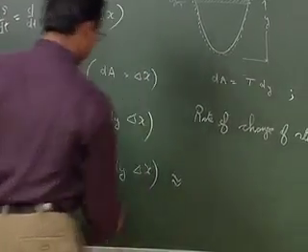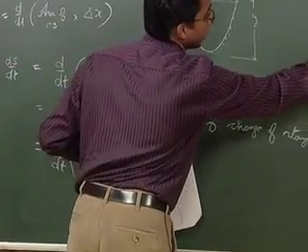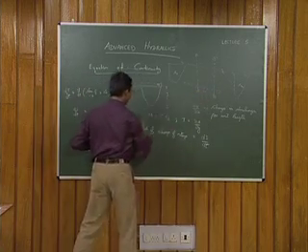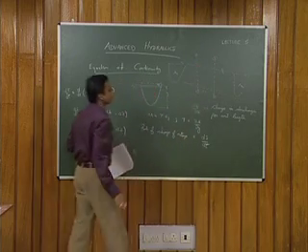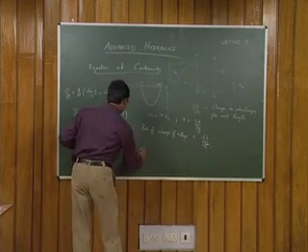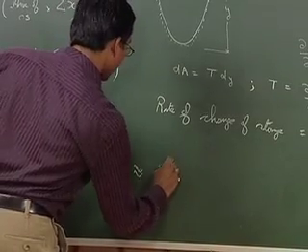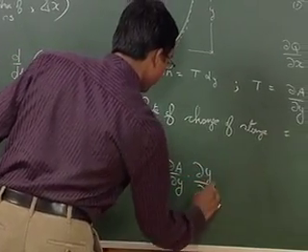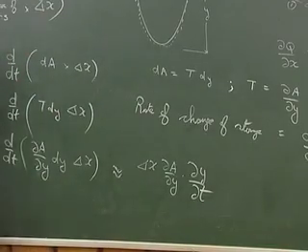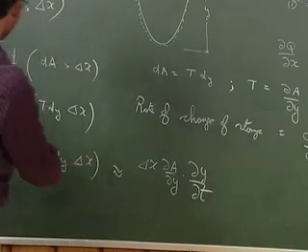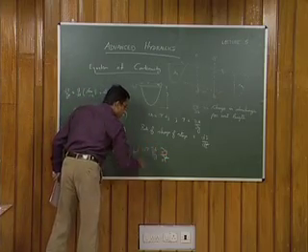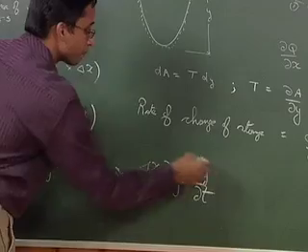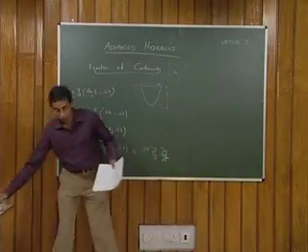This can be approximated now. We are suggesting, because we have just taken an arbitrary length delta x, which is not varying with time. That is delta x, it is for our convenience we have taken some length. This can be approximated subsequently as delta x dou A by dou y into dou y by dou t, that is the change in depth of flow. Your storage has now become a function of change in depth of the flow. So, ds by dt is now approximated as delta x dou A by dou y into dou y by dou t.